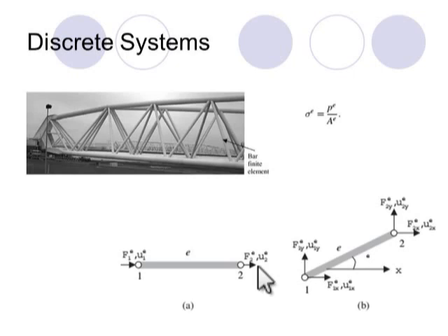Of course, many of my problems are not one-dimensional. Sometimes I can say that my problem is two-dimensional. In such a case, I have two force components and two displacement components at each node, and certainly my truss element has a direction.